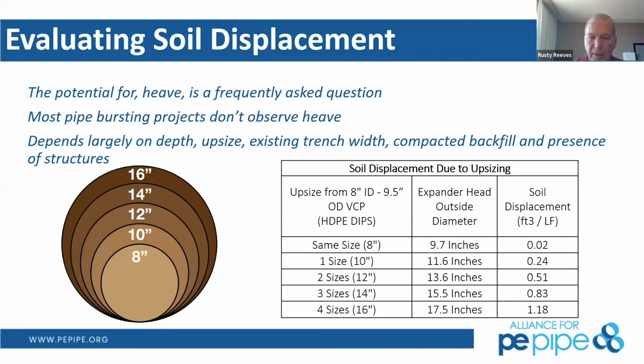So a lot of those questions would have to be answered by your pipe bursting contractor. But I mean, we've seen jobs go on, upsize 2 and 3 times the pipe size. So it's very possible, depending on your materials there. Oh, yeah. For third-party utilities, when we know about it by doing potholing before that process comes through, we remove any soil that could push into that third-party utility, so that there's not a direct conflict.